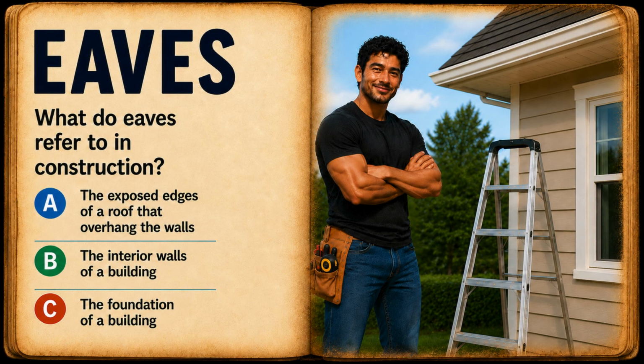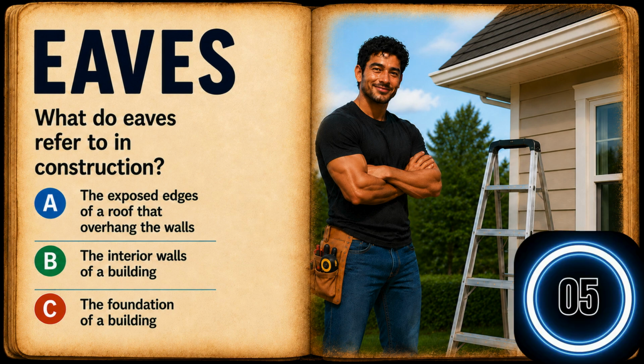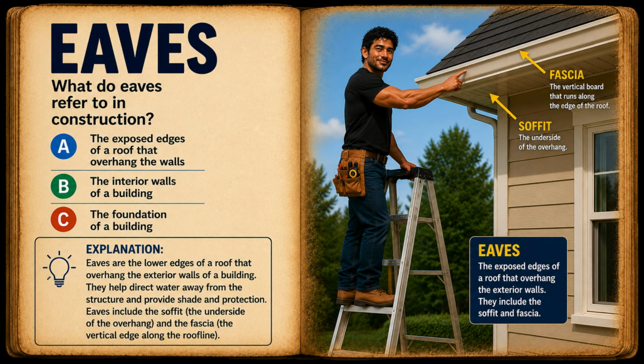What do eaves refer to in construction? A, the exposed edges of a roof that overhang the walls, B, the interior walls of a building, or C, the foundation of a building. The answer is A, the exposed edges of a roof that overhang the walls. Eaves are the lower edges of a roof that overhang the exterior walls of a building. They help direct water away from the structure and provide shade and protection. Eaves include the soffit, the underside of the roof overhang, and the fascia, the vertical edge along the roof line.